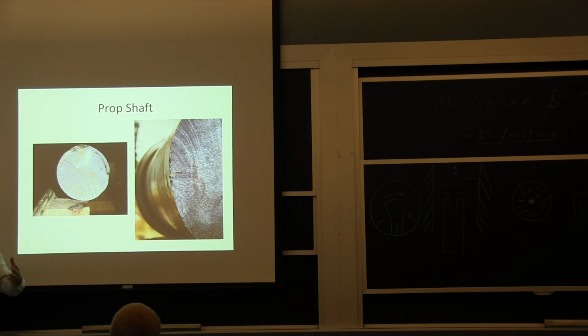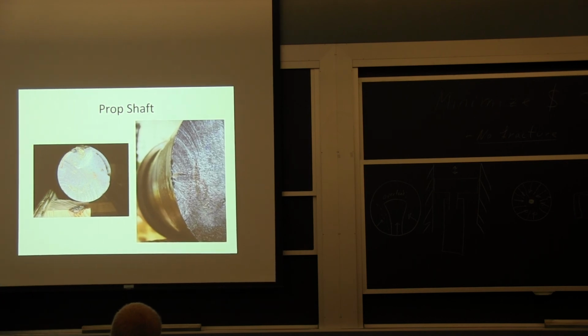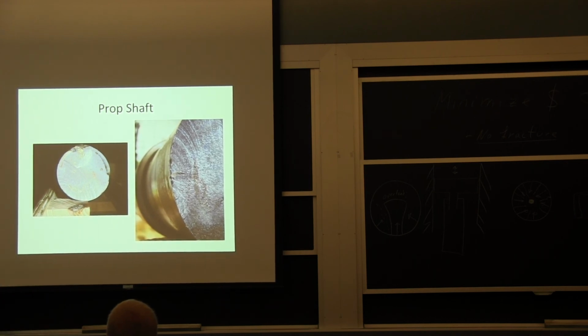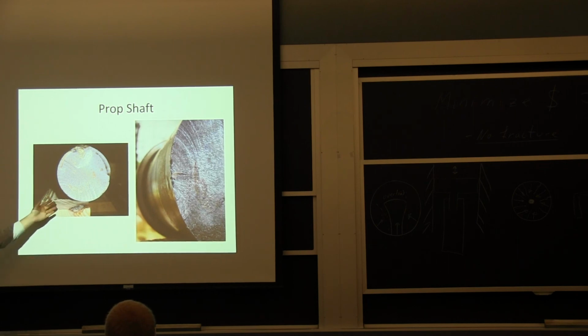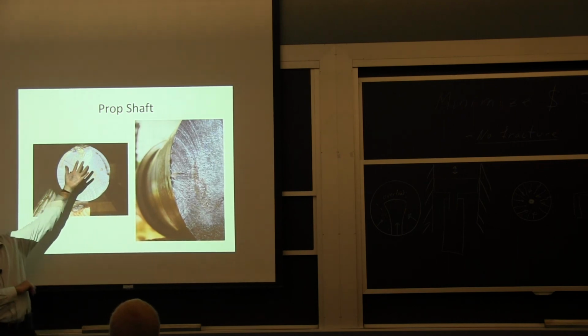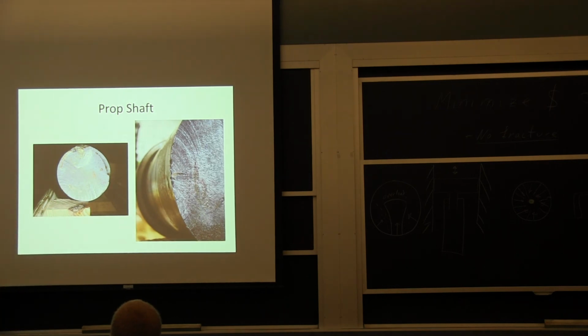I mean, there may be a little effect of where exactly the blade is on the prop, but overall, as you turn, you always had a bending moment and a torque. Normally the torque can matter, but in this case it really didn't, because this was perfectly transverse through the material. And it's a large section at 7 inches. It's a powerful engine, I'm sure, but it was really a bending situation.